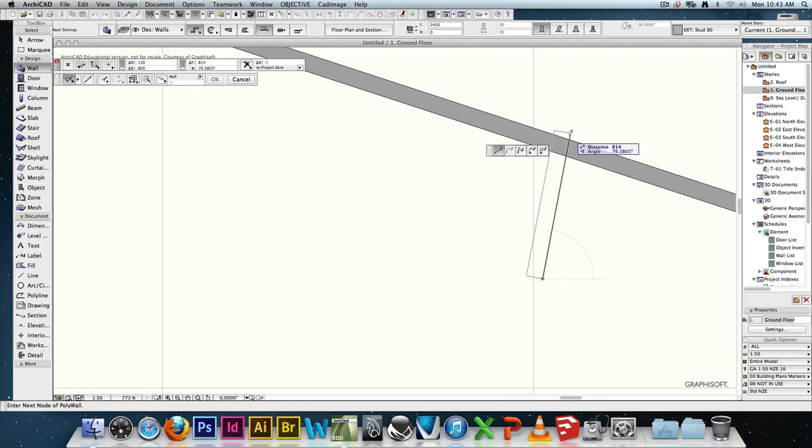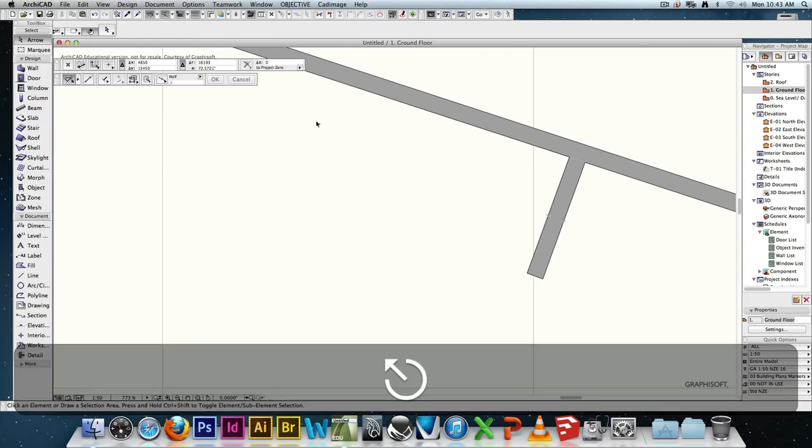It doesn't tend to happen to things that are vertical or horizontal. But things that are on an angle, it nearly always happens, because what's the chances that your snap grid aligns perfectly with that line going through the same space? You know, pretty much zero. So if you're finding that things just aren't snapping together, that's probably why. I mean, the software is relatively smart.